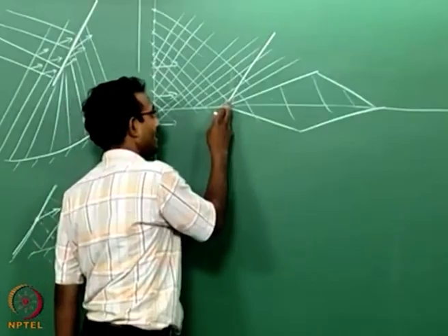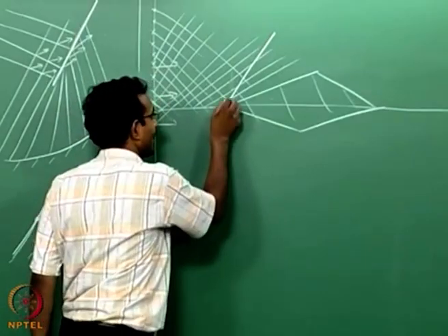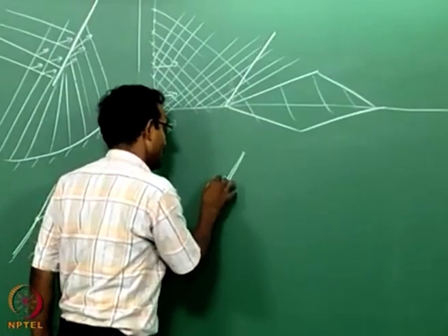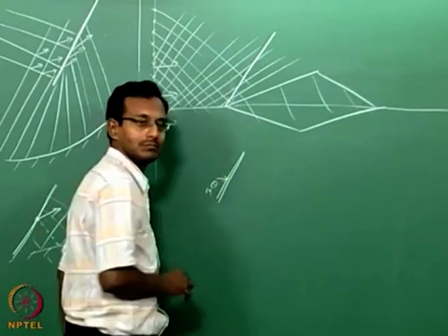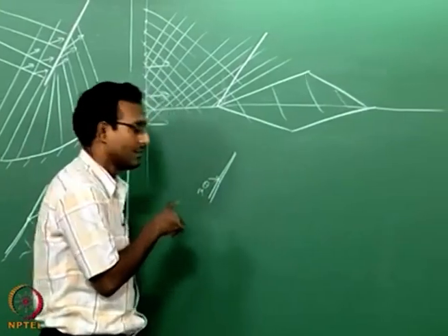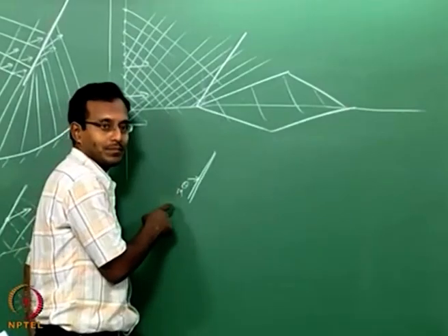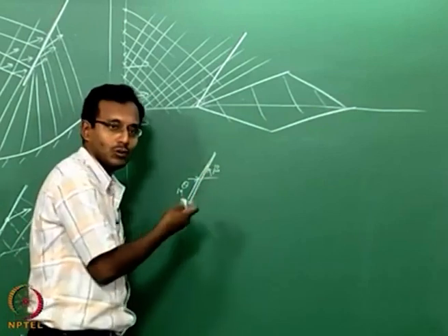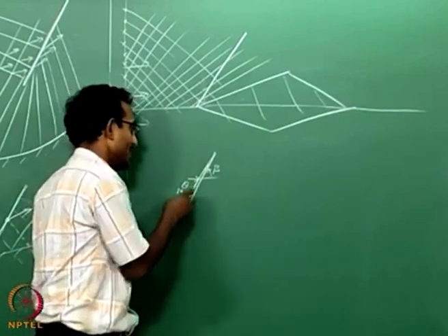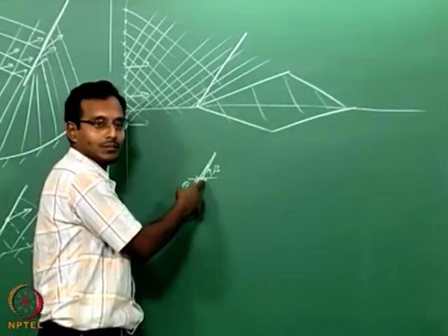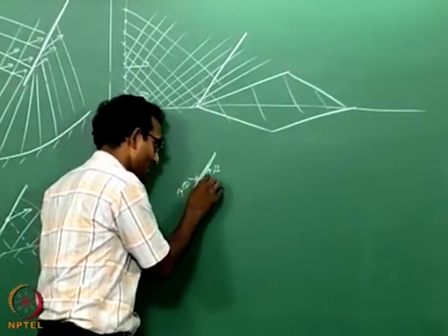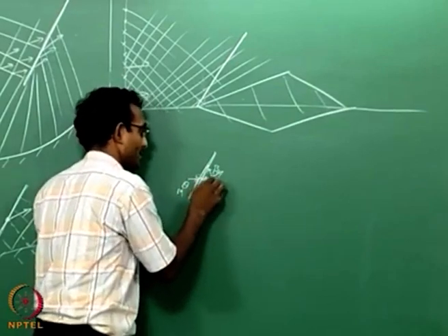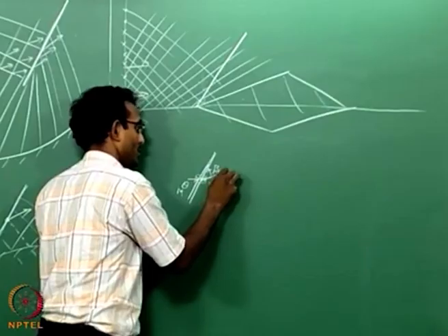I will calculate that point and then I will look at that local region. What is that local region looking like? It is a shock with incoming theta known, and incoming Mach number known at that location xy. Once I know theta and M, and I know the local angle beta, the oblique shock angle, I can calculate the downstream conditions of the same shock at the same location. So it will finally be going with some other theta and some other Mach number, M2 and theta 2.